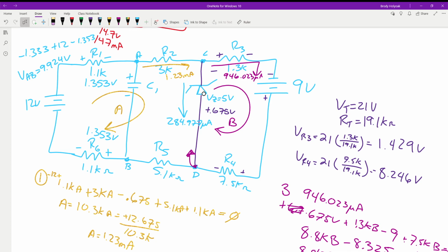So then basically what we have to do then is that 5 volts, then the rest of that voltage is going to get split out across those 2 resistors, which is what we find when we go through our Kirchhoff current or Kirchhoff voltage law. So again, this one's a good one because this incorporates the capacitors. What does it do? Incorporates the diodes. How do they work? We have Kirchhoff's voltage law. We have Kirchhoff's current law. We have Ohm's law. Really, the only things we didn't solve for was power. But in this case, I'm not too worried with microamps.